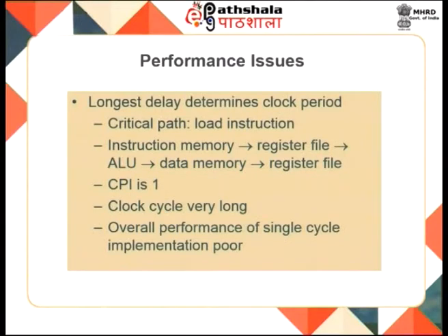The longest instruction from the subset of instructions that we have looked at is the load instruction, where you will have to read the instruction from the instruction memory, which is the critical path. You will have to read the register file, go to the ALU for effective address calculation, access the data memory for getting the operand from memory, and then write it back into your register file.